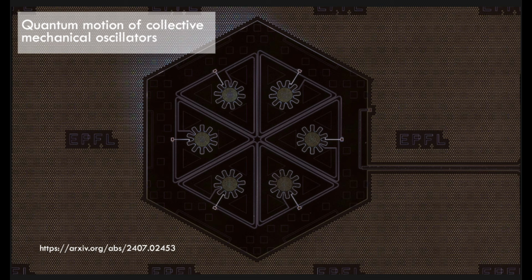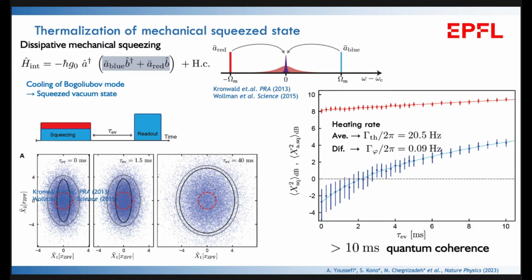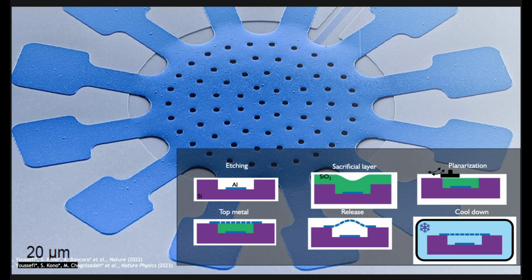dissipative couplings between them? So the damping in this case, in these devices, is still only controlled very rudimentarily. So we do a bit of what we call clamp tapering. We can change the aspect ratio of the clamps. I should say we still don't have a very good understanding of what exactly the loss dilution factor is in these planar devices, especially as temperature reduces, we don't know exactly what the strain is that we have generated. But aluminum that we're using here as a top plate is amorphous, it has grain boundaries. In that sense, there must be a significant amount of loss dilution occurring,